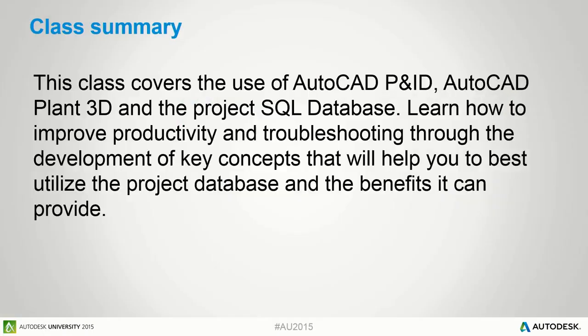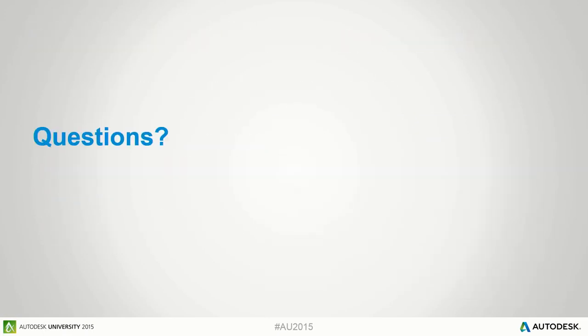Data changes. One thing I thought maybe worth mentioning: if you have to edit a large number of drawings, and you try to export out of the data manager and then import back in, you find the program wants to crash. Has anybody ever had a crash on it? Oh yeah. But that's why it has that two-step import. You import it and then you accept the modified data. So if it crashes before you hit accept, it should default back.